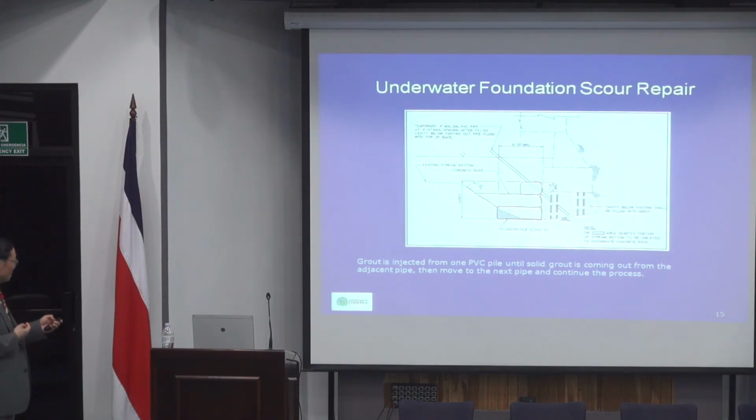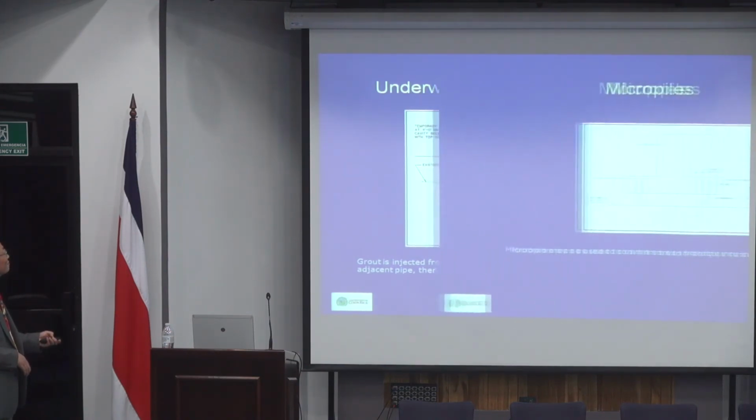Underwater repair, again as we discussed earlier, you can simply block these scour areas. I typically use concrete bags. Concrete bags lay down much more nicely than regular riprap stone, so that once I do that, I can pump grout into the footings.